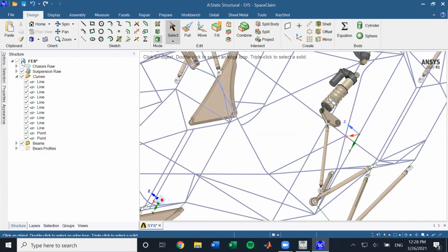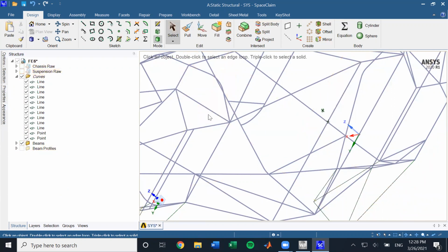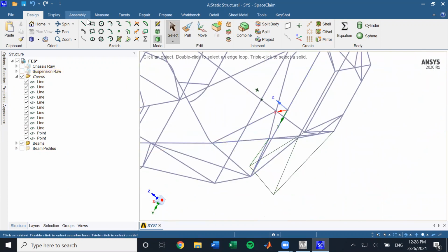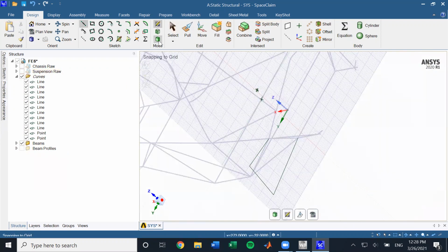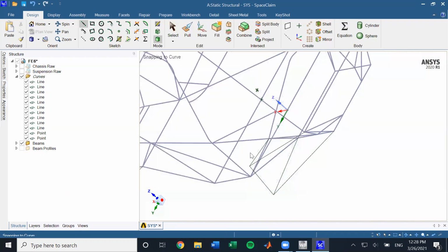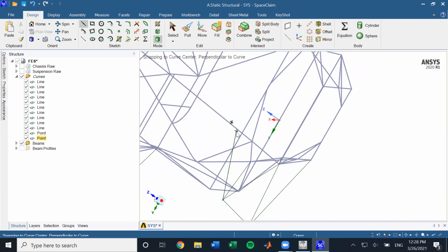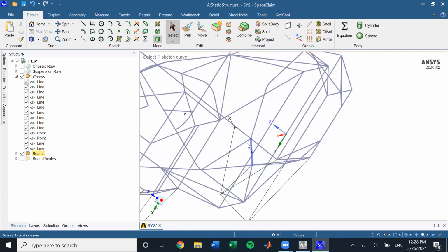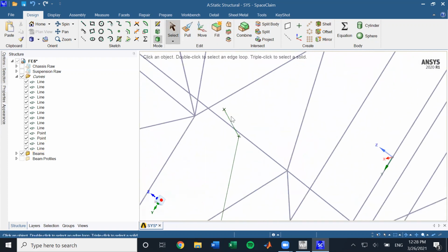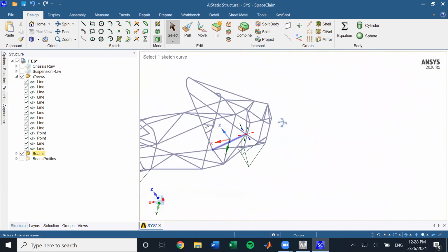Yeah, and so now let's again hide our raw suspension, and we can draw a line in 3D mode from here to our push rod rocker pickup, and then another one from the push rod rocker pickup to the spring rocker pickup. So essentially, we now have drawn our push rod and also our rocker in the rear.